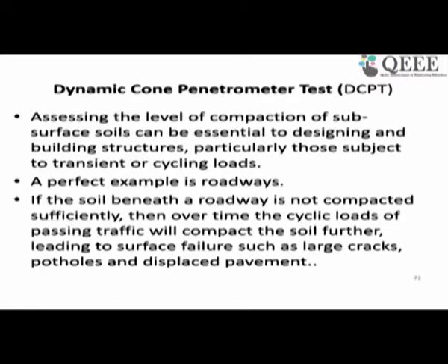Then the next phase is the CPT, where the cone is penetrated with a mechanically operated machine, and then we use sensors to get the values of slip friction and tip resistance. The third case we saw was the CPTU, where we added the pore pressure measurement. Then next we saw the SCPT, where we also had a seismic cone penetration.